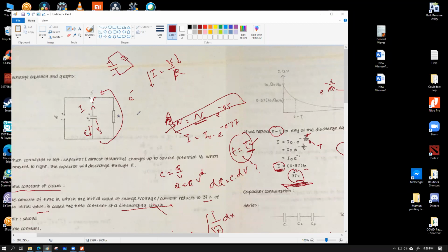As the capacitor is discharging more, the available voltage across its space is becoming small. So the current is also becoming small. As the current is becoming small, it is discharging even less. So it is never discharging completely to get rid of all of its charge. Because the further it discharges, the drive to discharge is becoming less. Like eating kachi, that example that I pulled out last class. The more I eat, the slower I eat because I don't have to eat faster.